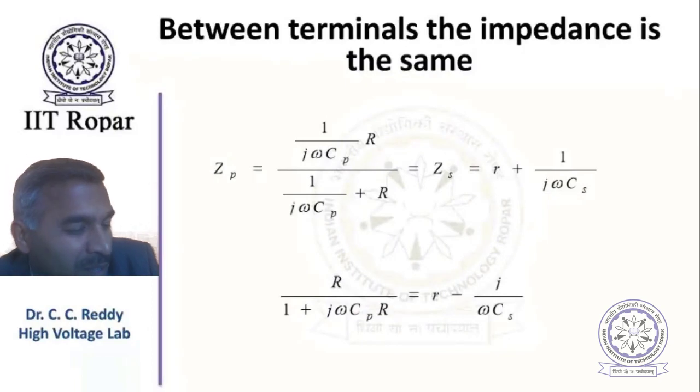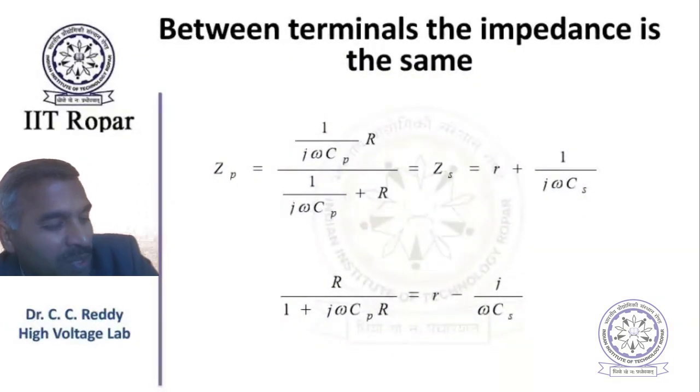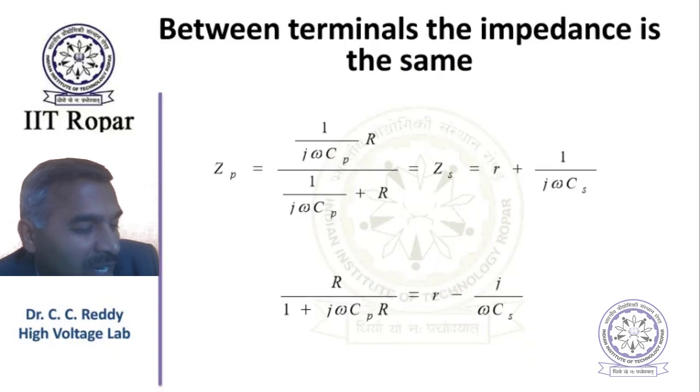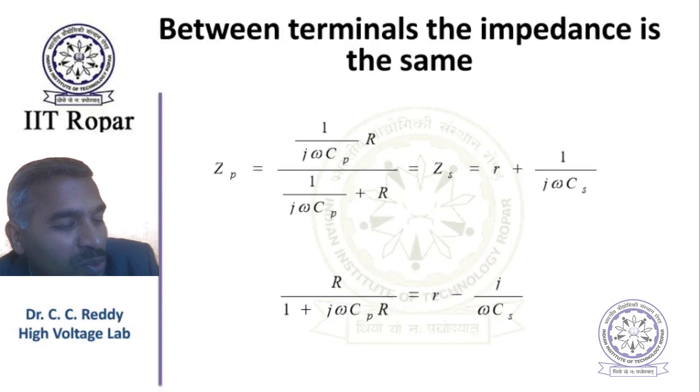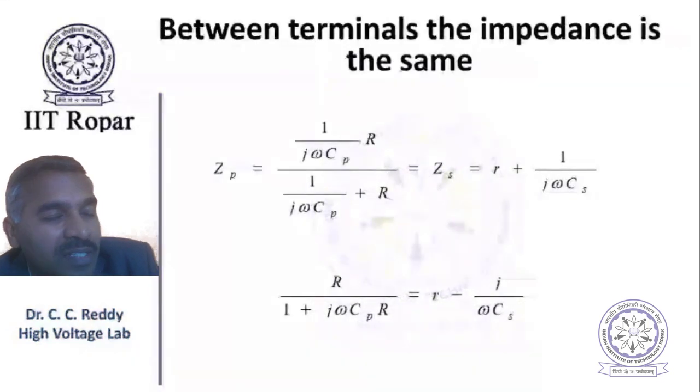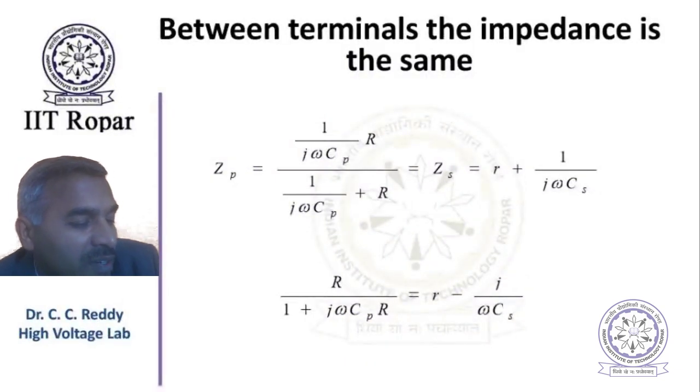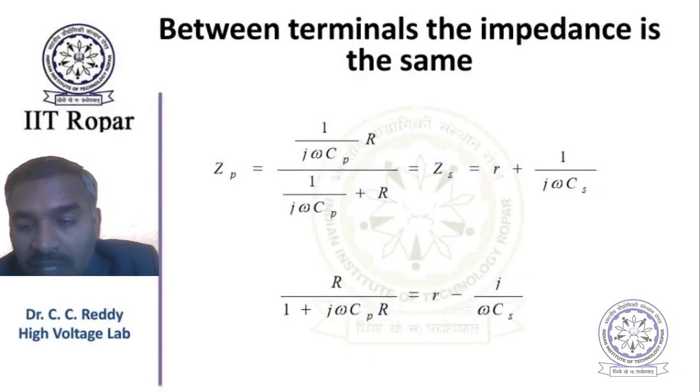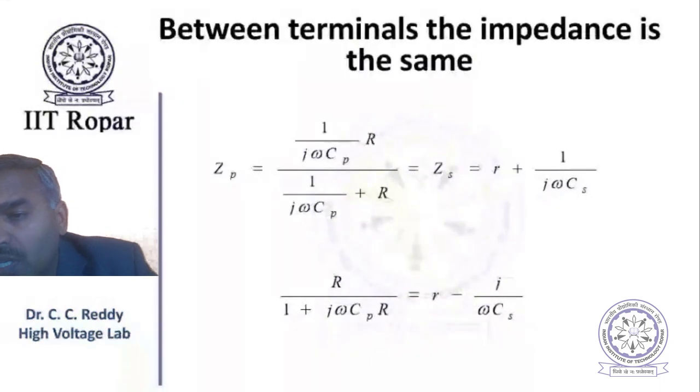It is defined for a particular frequency, for AC. For the DC case, the lossy representation is only for representing the losses. That equivalent circuit is used for circuit analysis, but tan delta is not defined for DC. Tan delta is defined for power frequency and other, higher frequencies. Normally we refer to power frequency only.